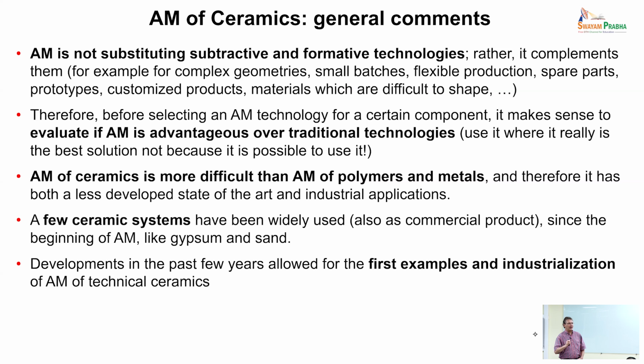So the message here is that if you are an industrialist or if you are a researcher, you do not need to immediately think that, oh, I want to make the part using additive manufacturing. You have to use additive manufacturing only when it makes sense in terms of shapes, in terms of properties, in terms of cost. So you need to definitely evaluate if it is advantageous to use additive manufacturing rather than conventional technologies.